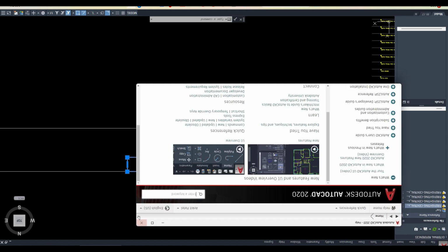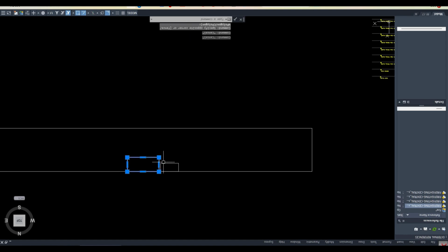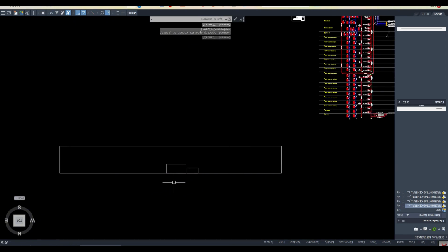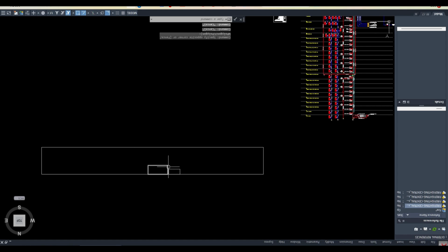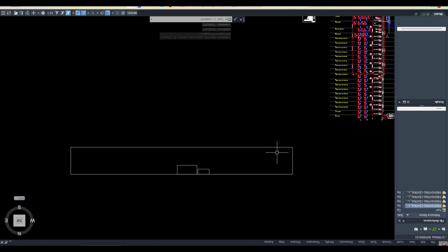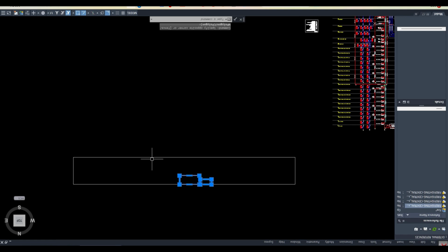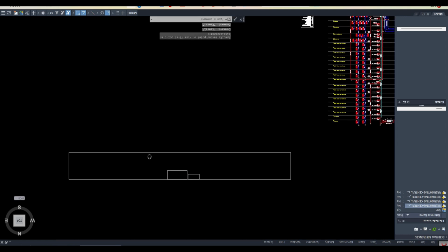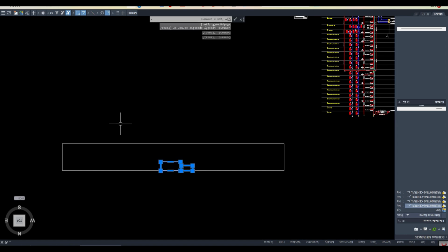Now here is the staircase. I'm keeping my hose reel together with the staircase, so it's not more than 6 meter, right? Let's say our complete corridor is 45 meter. So from here anywhere he goes, he can reach, right? If the total is 45 meter, the half of that is how much? 22.5, right? So it is within the 30 meter range, which means it can cover this side and this side also. Let's say this is in the mid. So how is it wrong? Logically tell me.